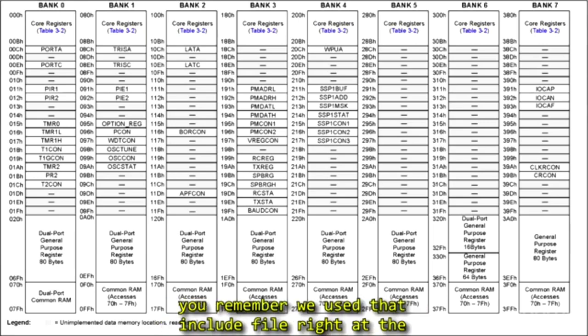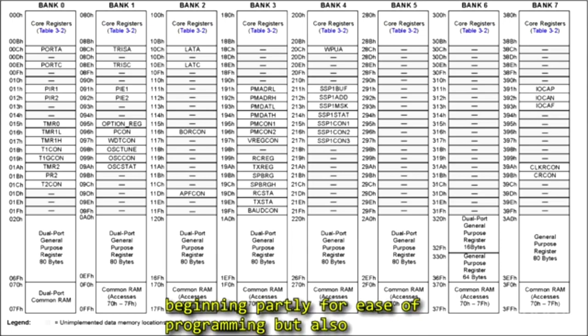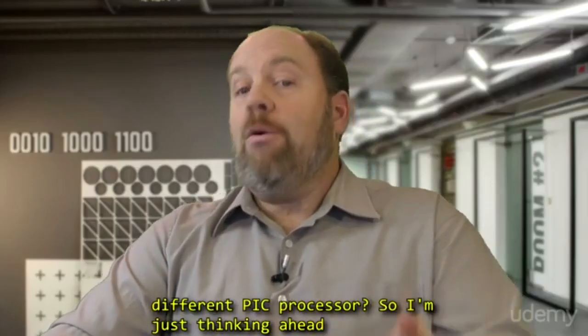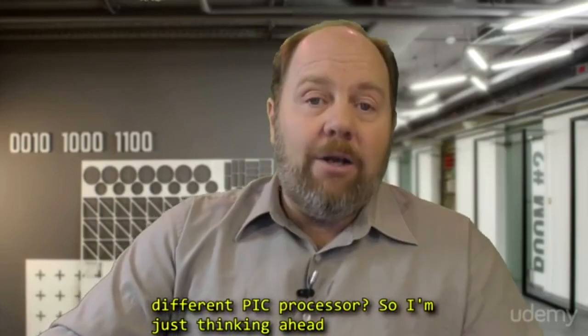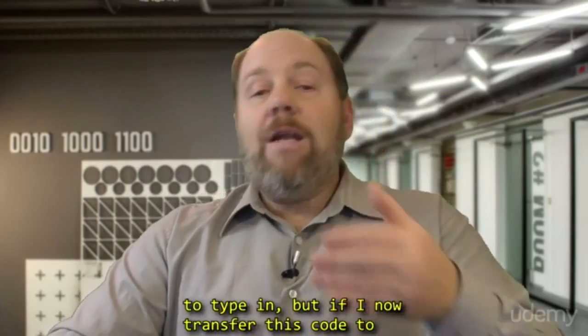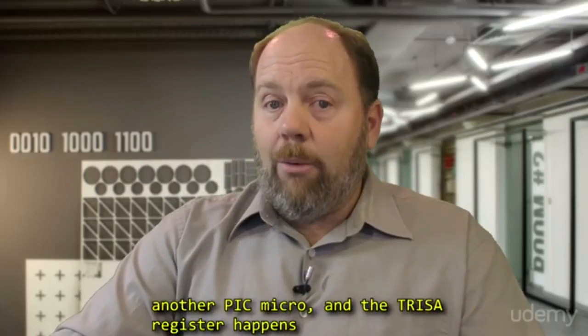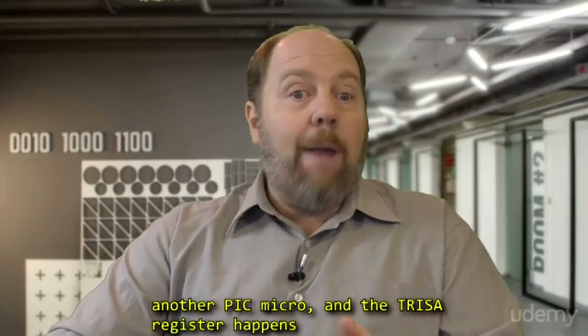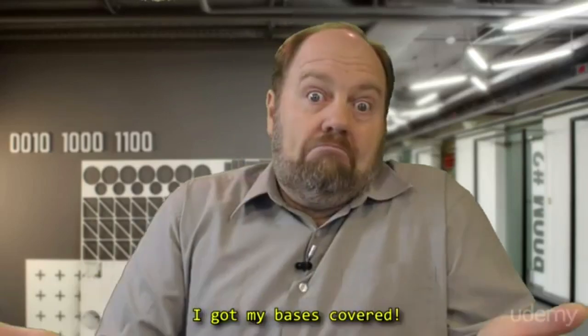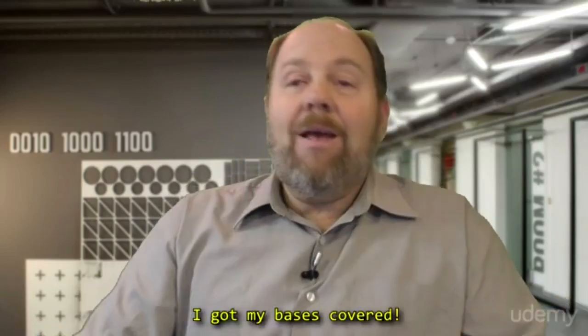However, you remember we used that include file right at the beginning for ease of use, so ease of programming, but also so we could transfer this program to another different PIC processor. So I'm just thinking ahead here. It's a single line of code, not a lot of work to type in, but if I now transfer this code to another PIC micro, and the TRISA register happens to be in a different bank than the TRISC register, I got my bases covered.